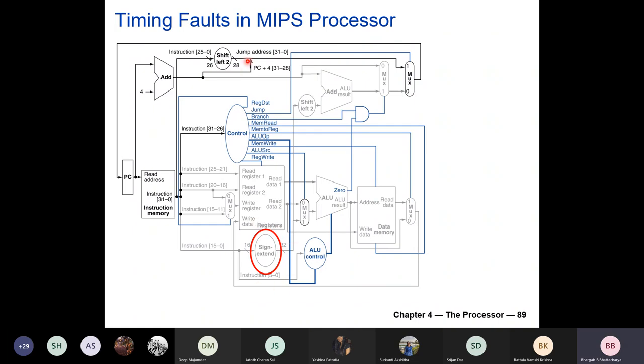There are many reasons because of which this delay might increase. For example, if you are using the chip continuously, it might heat up. And when it becomes heated, the transitions from 0 to 1 and 1 to 0 slow down. And there are also many other problems. There may be some other defects for which the signal flows slowly, I mean, the insertion of some kind of delay. Capacitances might increase because of some manufacturing defect. So they are not stuck at 0 or 1, but when you are applying a 16-bit offset here, you are getting 32 bits, fine, but after a certain delay.